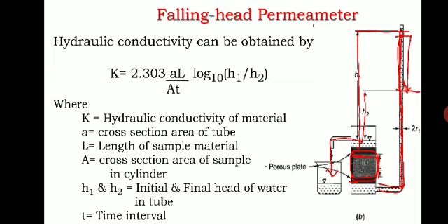So getting the undisturbed sample is very difficult, while in the disturbed sample experiment, sometimes there are changes in the porosity or packing of the grains. Okay, so there may be chances of error for the actual reading. Then the flow direction properties of K may not be recognized. So these are the disadvantages of the laboratory method.